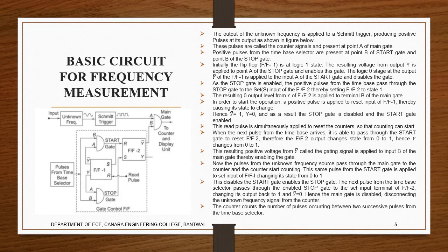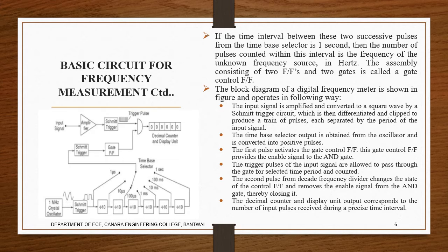So what is the counter? The pulses occurring between the two successive pulses from the time-based selector, whatever they are, are counted at the counter. Okay, so this is the basic frequency measurement circuit.